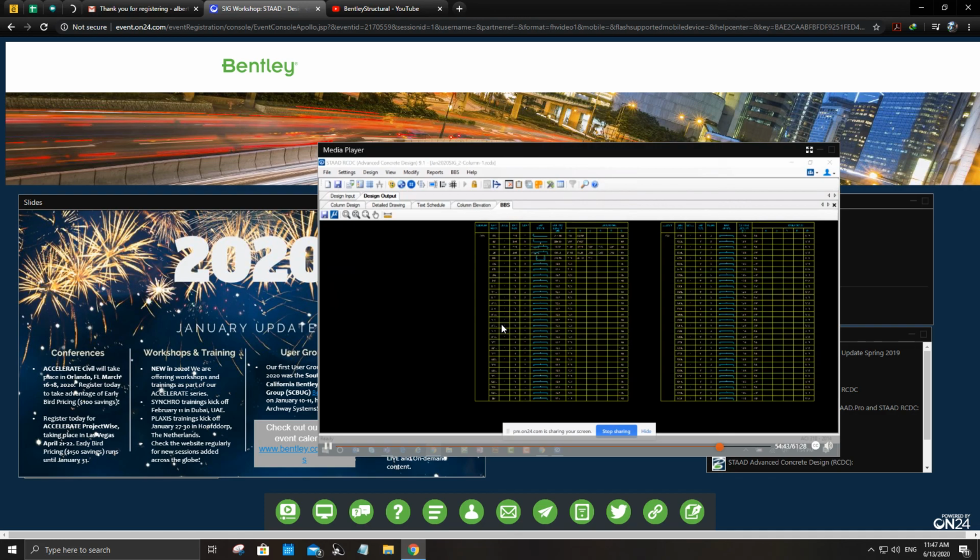And how do you make sure a slab is connected to a wall? I would say that this is the same as the similar thing. Whenever you have a 90-degree intersection, you can use a parametric surface to create your slab. But in order for it to be connected at the same nodes as the wall, I'd probably want to use the same mesh density or create the walls first, come back later and create the slab. So you can create a parametric model for your walls, commit them to the input file, and then come back to parametric and create more. So I would probably do that.